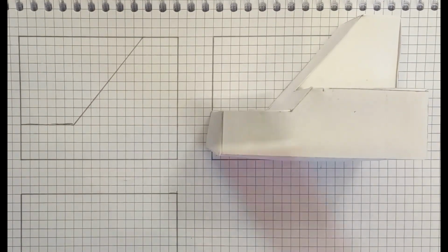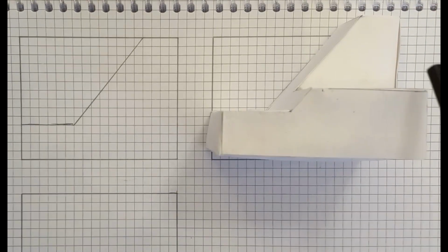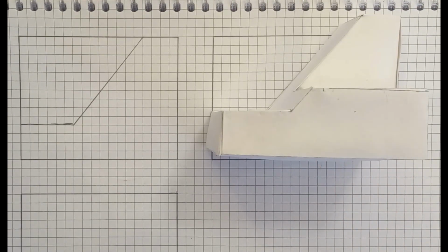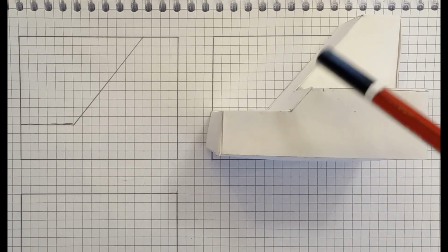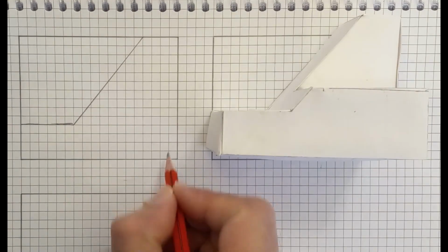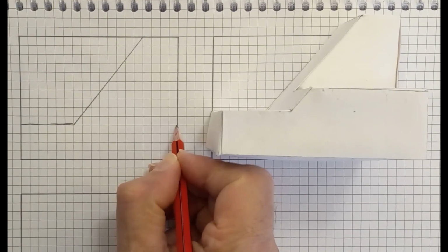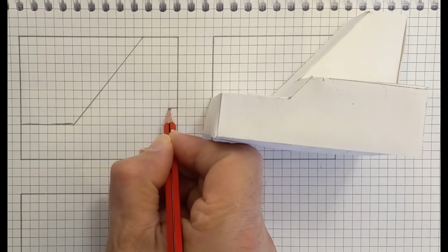This inclined line represents this line. This edge is represented by a horizontal line 30 millimeter from this point. So I will go from this point up 30 millimeter, then draw a horizontal line till it intersects the inclined line. From this point, go up 30 millimeter, 10, 20, 30, then draw a horizontal line like this.